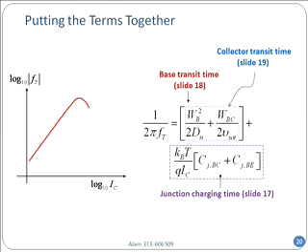This is exactly what happened in the mid-60s. People used to make this transistor, measured them in their lab, and they would see a turnover. Nobody understood it. The best minds at that time, all the big industrial labs, Sony, IBM, TI, scientists were looking all over for what it could be that I cannot push my frequency anymore. And Kirk explained that effect, and that's why the effect is named after him. He was the first one to suggest how excessive collector current can overwhelm WB, and as a result, it will roll over.